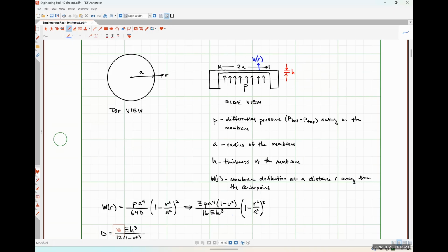As we get to the center, the top surface is actually going to be under compressive stress now, and the bottom surface is going to be under tensile stress as it's getting stretched out. So there's going to be lots of plus and minuses in the stuff that I'm about to give you, because one surface is in tensile and one is in compressive stress.